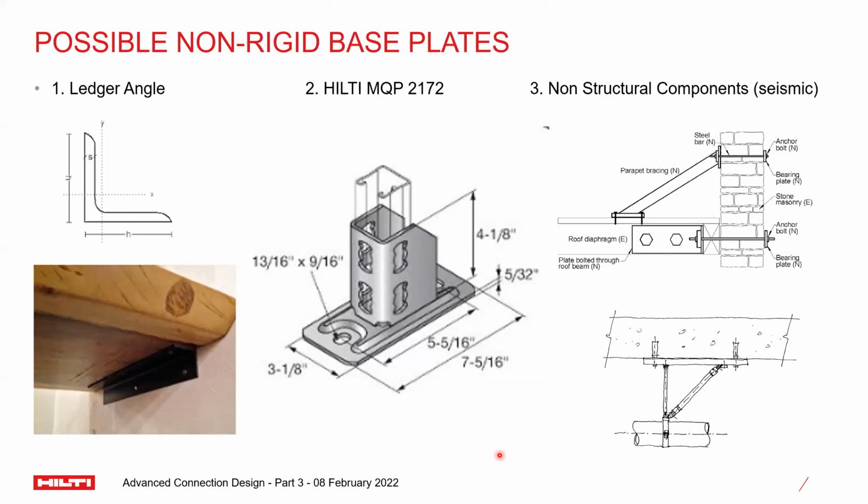I mean, installation systems, or we call them again modular support systems, and this is approximately 4 millimeters thick. If your base plate is 4 millimeters thick, just think about it, 4 millimeters, how small it is. Would you really call this a rigid steel structure or rigid base plate when you apply really big loads on it?